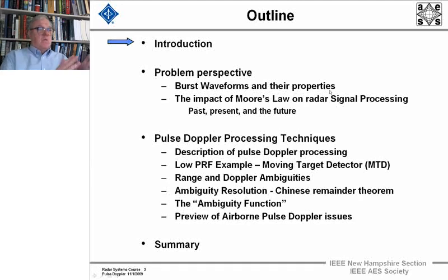That is to say, we don't just send out one or two pulses and listen to the echoes, but we might send out 100 or even 1,000 pulses in a burst, waiting for the echo after each one of the thousands, and take those samples at given ranges and process them through a linear process, multiplying them by weights to get the output of a specifically shaped filter, which will have specific frequency properties in the Doppler domain to optimize our detection.